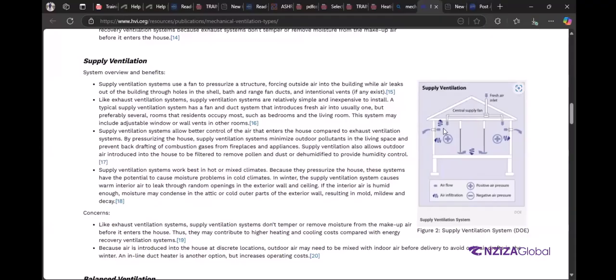So when the air enters the space, it is called positive pressure. It creates the positive pressure. When we supply air inside the place, we create positive pressure. So part of the supplied air is moving through the building. If we have small cracks in the building, or small gaps on the doors and the windows, a portion of the air is moving out. That process is called air infiltration. So part of the air remains, and another part of the air escapes from the building envelope.